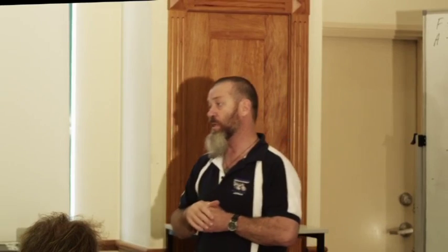Now, don't answer this because I already know the answer. How many times have you been tightening up an expanding masonry anchor, read Dynabolt, and you just keep tightening it up and tightening it up and tightening it up, and in the end you give up and walk away from it? I know, it's a lot of the time. And what you've actually done, because it's an expanding masonry anchor, is you've split the slab on the edge. You've cracked the slab. It's an ineffective tie-down connection. It was a complete wasted exercise.